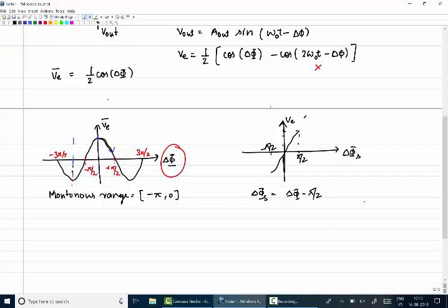You can also think that if the PLL is going to lock, where I have a 0 frequency error at the input and output, like omega in and omega out, both the frequencies are the same to begin with, then the PLL should lock to a 0 frequency error, 0 phase error in a type 1 PLL, right? If I give a positive frequency error, it is going to lock to a positive phase error. If I give a negative frequency error, it is going to lock to a negative steady state phase error. That's why I always try to consider this centered at 0.